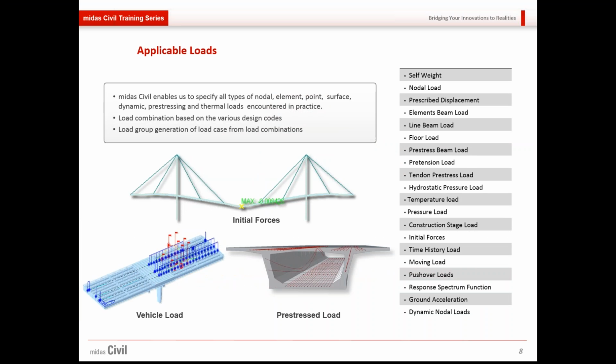In this webinar series, we'll be covering the self-weight, the pre-stressing loads, the SIDL for the wearing course, the temperature, that is element temperature, temperature gradient, as well as the moving load. However, the moving load would be covered in tomorrow's session. Today we'll be dealing with the temperature loads and SIDL loads, as the pre-stressing load, self-weight, and other loads were already defined in the previous session.